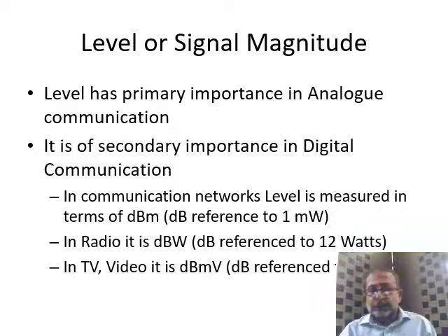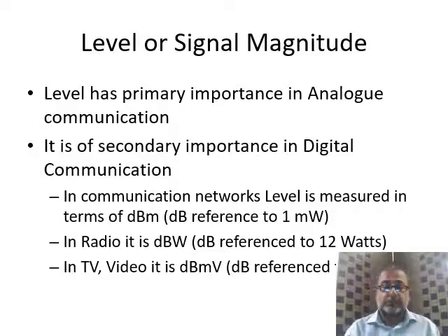In communication networks, the level is measured in terms of dBm, where dBm is the dB's reference to 1 milliwatt. In the radio side, it is measured in dBW, which means the dB's reference to 1 watt. In TV or the video, it is measured in terms of dBmV or the dB's reference to 1 millivolt.